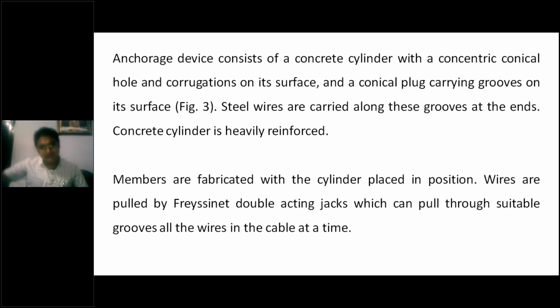Okay, the video you have seen just now, that system is completely based on the Freyssinet system only. Okay, the Freyssinet double acting jack is used for pulling strands through the bearing cone and bearing plate, where the wires are stretched within the cable at a certain time.